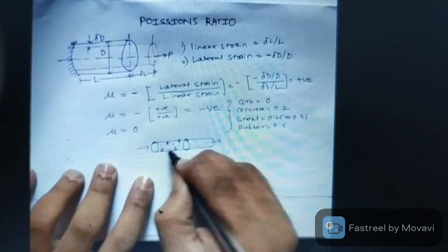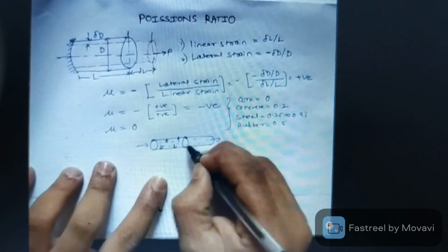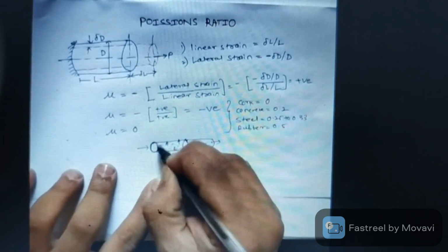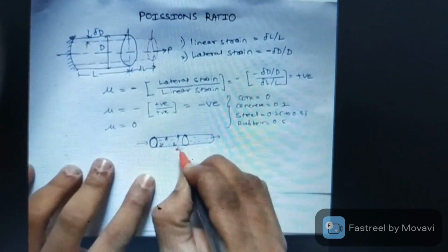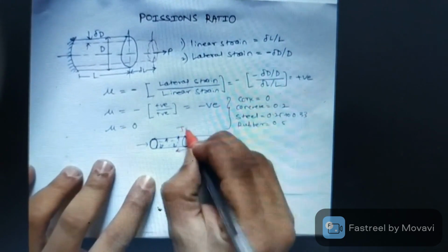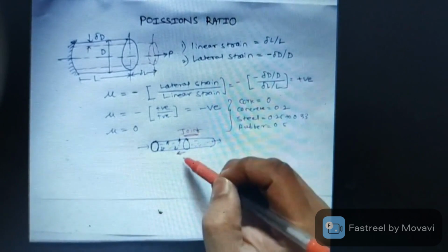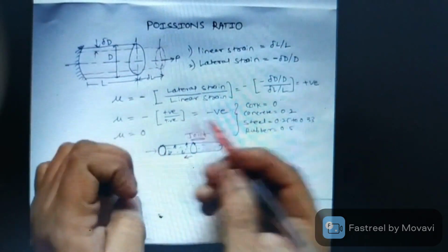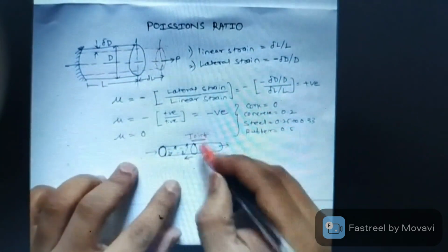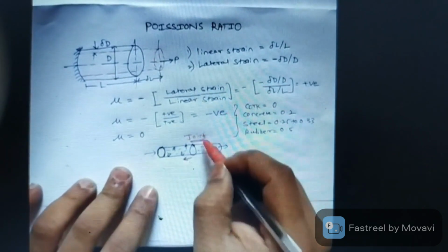That means the stress tries to increase the pipe diameter, and because of which the length tries to get reduced, and this is the joint. So this joint can fail if this strain is higher, that means if the compression of these pipes is higher, then the pipe can fail at the joint. So it is very important to consider this.